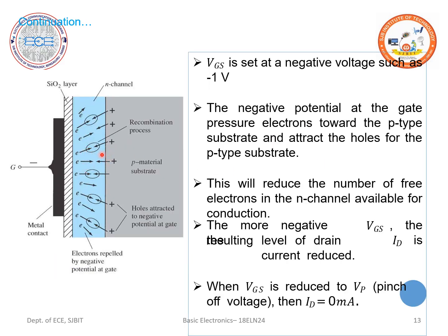So look here, since it is an insulating layer, the capacitor effect is formed. The metal surface which is the gate, and the conducting substrate below, are going to act as capacitor plates. When a positive charge is applied to one plate of the capacitor, a corresponding negative charge is induced on the opposite plate due to the electric field between the plates.